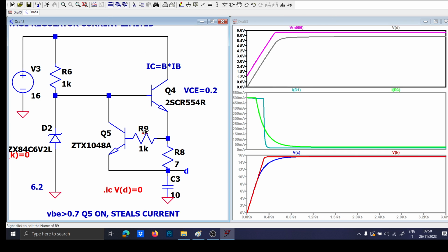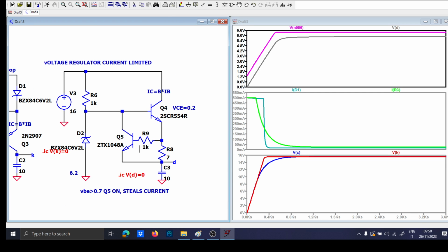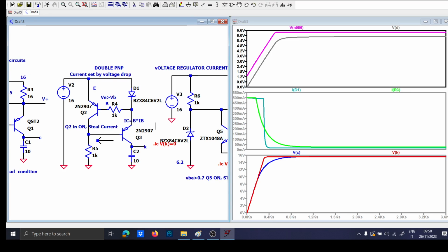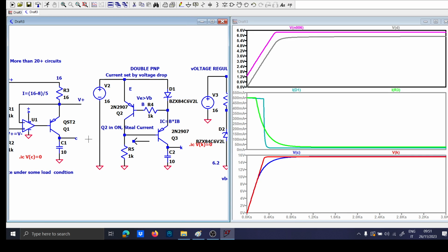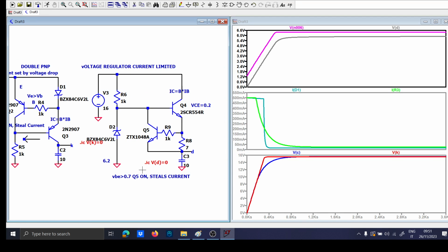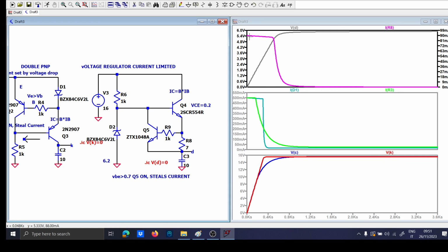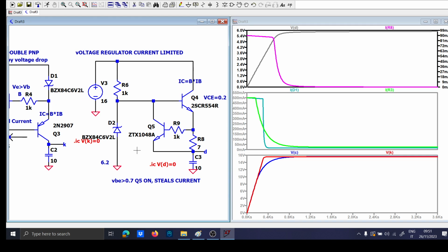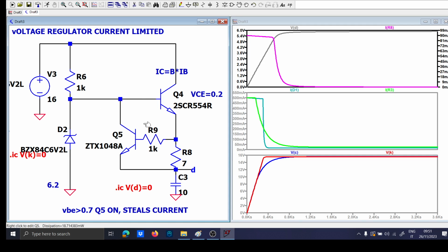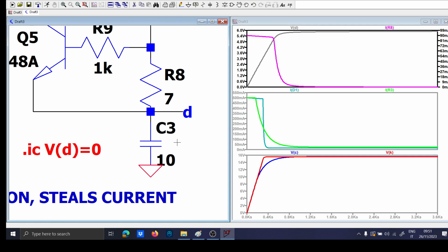Okay, the VC of this guy. But by the way, now I have achieved both the things that I wanted to do in the previous circuit. First, I'm clamping the voltage of this guy here, and second, I'm also clamping the current. So I have a current controlled and voltage clamping load, which is the best that you can achieve with just two components, two NPN transistors and just a Zener. So you can simply realize the circuit here and put the load here.